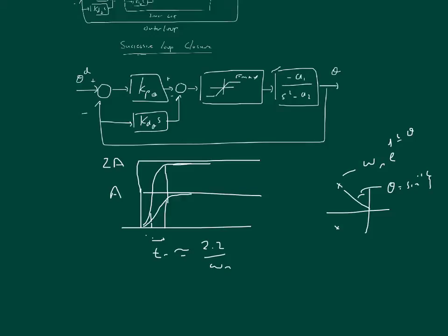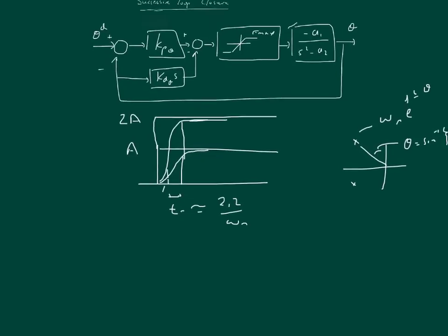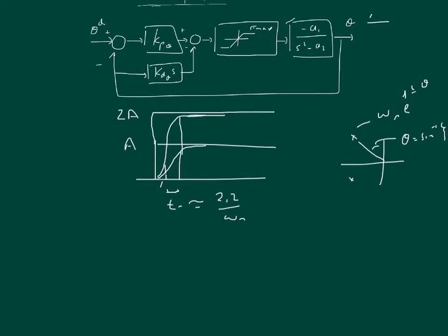So to get the fastest possible response you can get for a given step, subject to the constraints of F max, the objective, we need to choose Kp correctly. The way to reason about the system is to consider the case where theta of t is stationary for a period of time, and then you get a step of size A theta on theta desired.